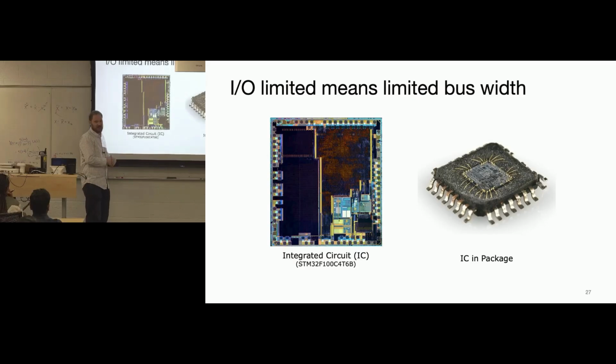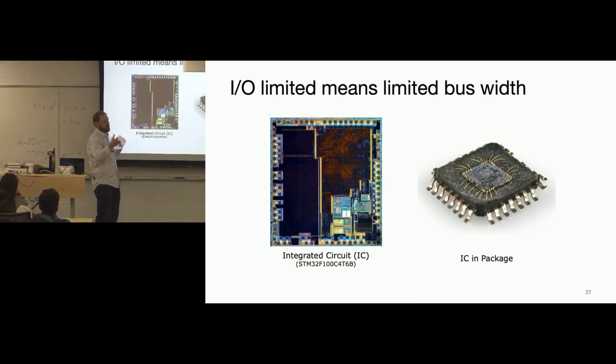So you have your UART peripheral, which is a communication peripheral. A timer won't work, but UART, ADCs, your camera peripheral, all these sorts of peripherals that live here, they reuse the pin for multiple functionalities.